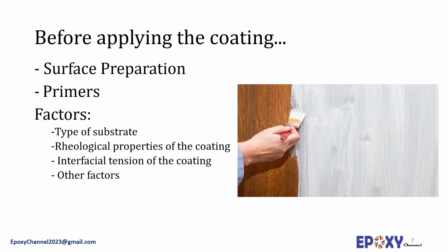If the aim of coating is more than just surface covering, some other specific treatments must also be considered. For example, to strengthen the glass surfaces, water vapor exposure to optimize the hydraulic durability of the coating is required. Primers also can be used to improve the wearability of the surface or for protection purposes, especially for hydrated surfaces. The primer must adhere well to the substrate surface and exhibit good bonding to the coating. Coupling agents, which react readily with inorganic substances, and the epoxy resins are also employed in primers in coating applications of inorganic substrates.